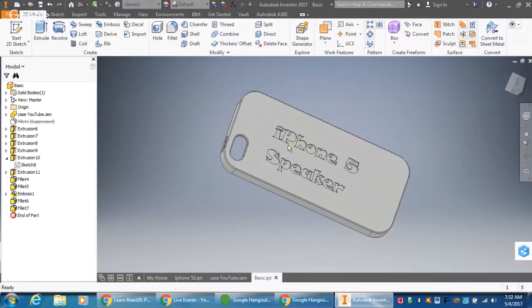And again, you can play with the designs on the back. If you watch the spinner videos, you can see how you can trace an image back there as well. You can cut it out, or you can just go to a simple extrude and extrude different shapes at different depths. So you can get multiple layers of depth and then just keep reusing the sketch of the image, and you can get some pretty complex images by doing it that way as well.